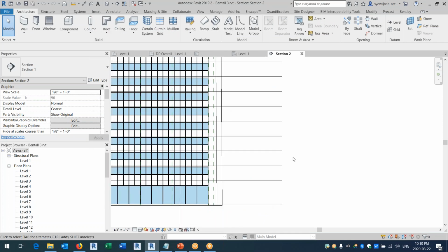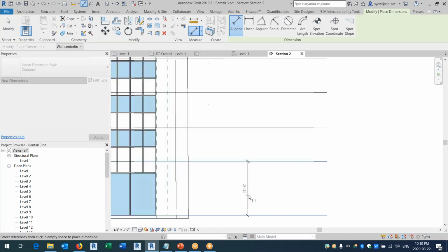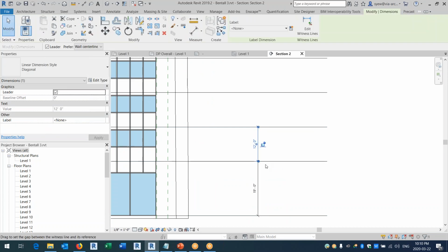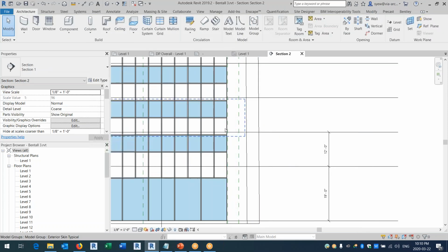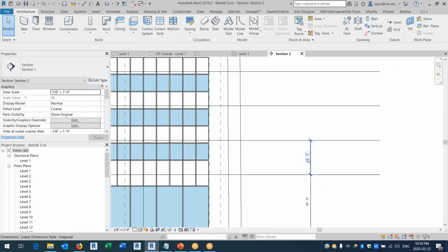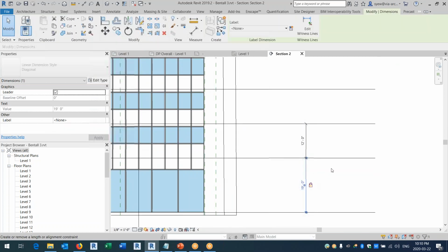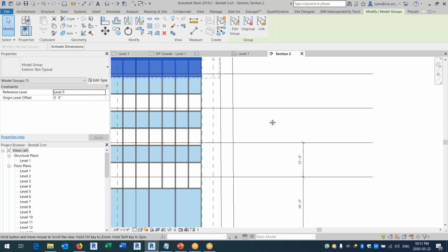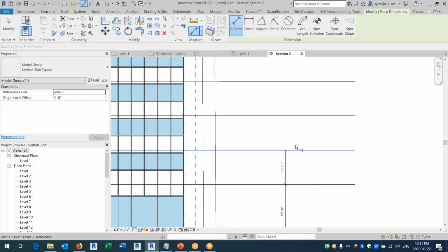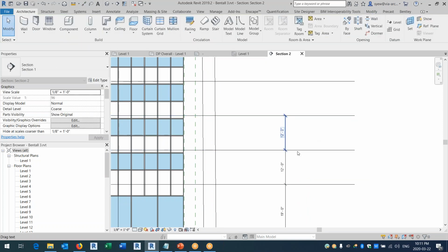Okay. So the first thing I would do is first you set up the height for one of them. Let's assume that this height is what I want to change, and the other one also as well. You notice that here I have multiple heights. So here I'm just going to leave it as it is. I'm just going to lock it so it won't change. So here I have multiple skin curtain walls that are 12 foot.